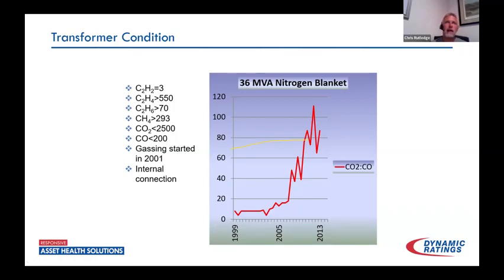So in my mind, that's indicating that whatever the heating is occurring in this transformer, probably not involving a lot of the solid insulation. As we saw before, where windings or where we're heating a lot of paper all at once, we tend to see pretty sharp drops in this ratio. However, something like a lead or a connection, that type of thing, really is not going to negatively impact this,